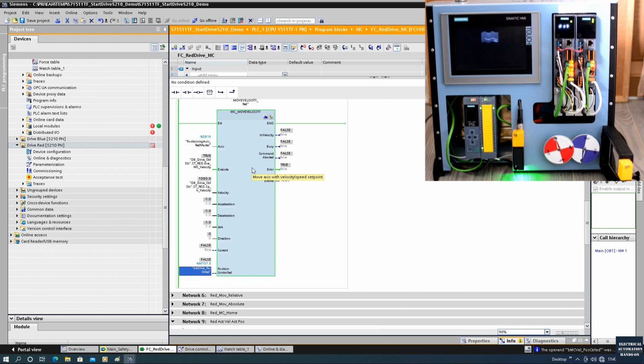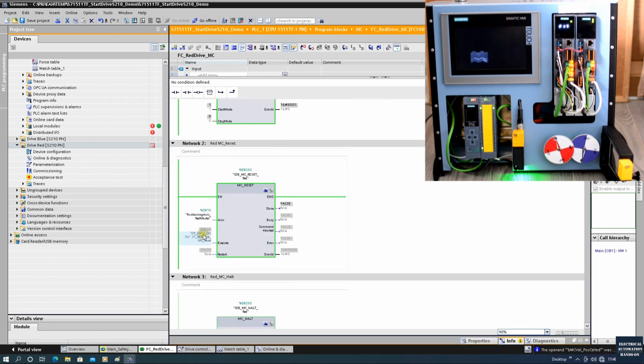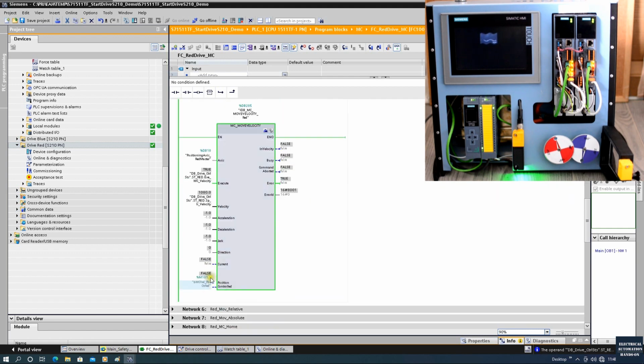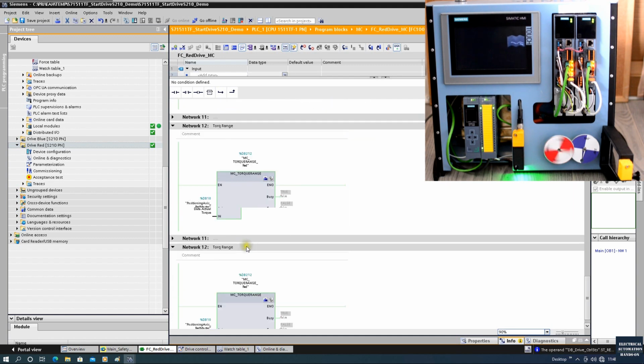So basically, while using the torque reduction control, in most cases, or 99% of cases, we will use the move velocity, doing the velocity control. So we need to kill this position loop, turn this off, okay? And then let's try it again. So firstly, reset this fault. Okay, now there's no fault. And I will trigger this move velocity, but this time I turn off this position control. Trigger again. Okay, motor spinning.